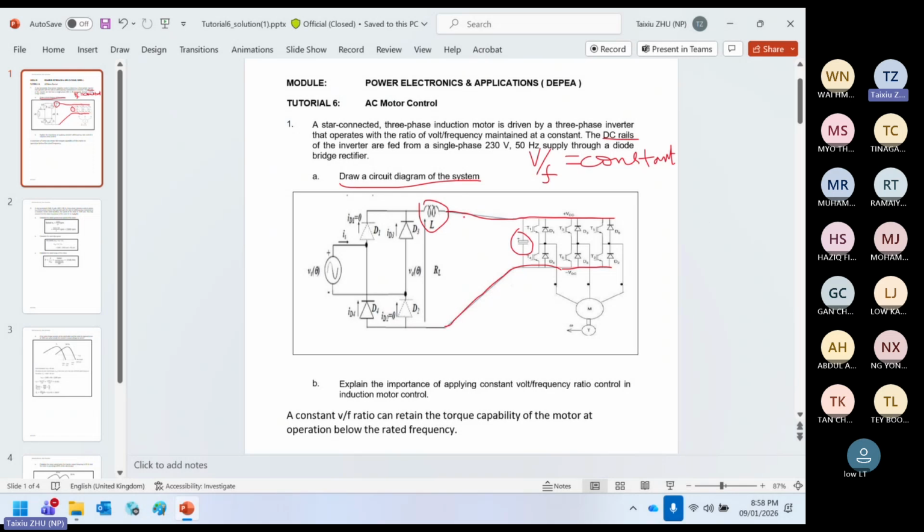That means very low frequency, like DC at frequency 0, can get through, and higher frequency harmonics are blocked out. So this is a typical LC filter, an inductor then a capacitor.